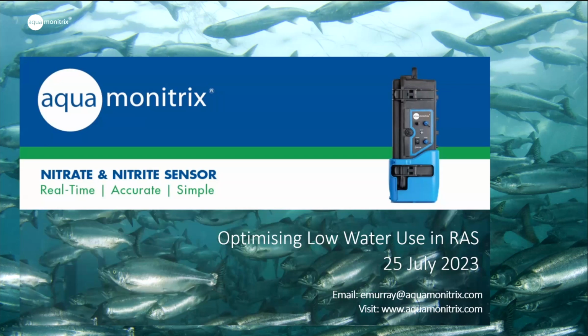system and taking the data from our analyzer. First of all, they're in the measurement phase, so they're measuring nitrite, nitrate. The next thing will be to use that data to look at things like optimizing the rate of dilution, preventing nitrite and nitrate accumulation, trying to control feed rates, trying to control all of those to keep the nitrite and nitrate numbers within safe parameters.